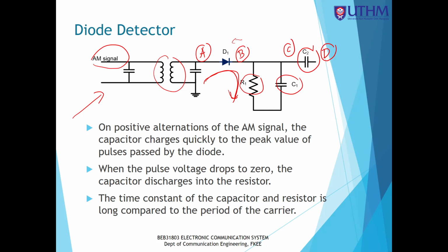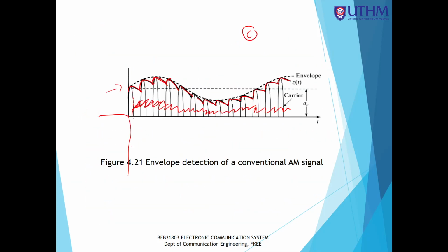Capacitor will remove the DC voltage. It allows only the AC voltage to flow. So that means what? You see that the graph now looks like a sine wave above a certain level. That means the DC voltage here, this is a DC level. Okay, the DC level is here. So what happened is that this capacitor C2 will remove the DC voltage.